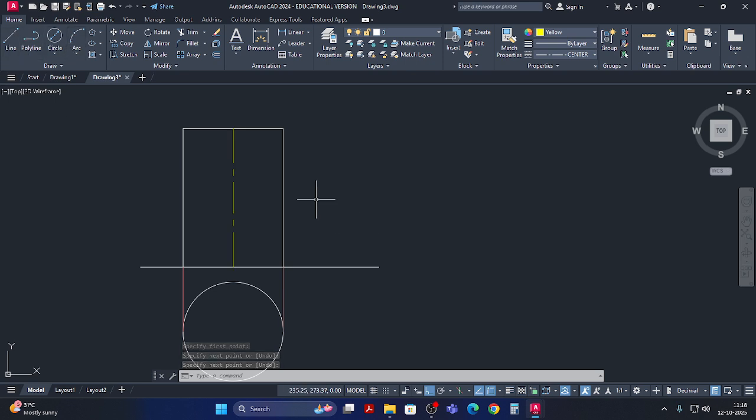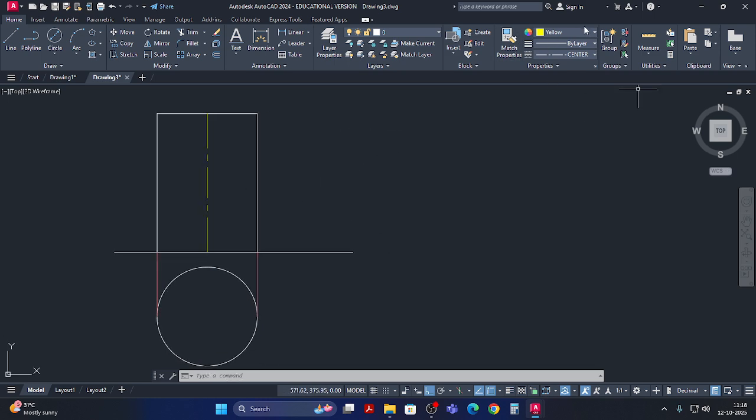Now let us draw the square hole in the center of the line. The hole is a white object. So take polygon directly. Number of sides 4, and edge. Draw it somewhere outside, then move it and keep it inside.